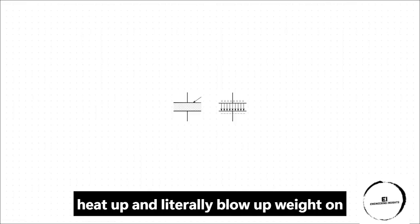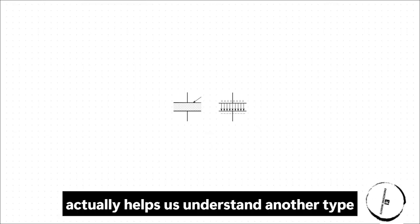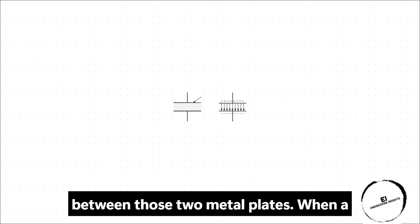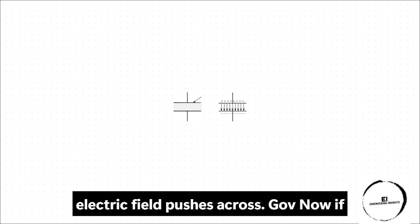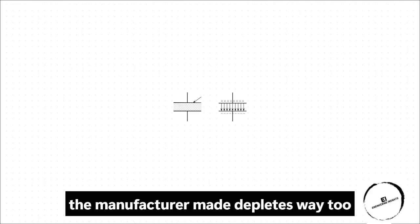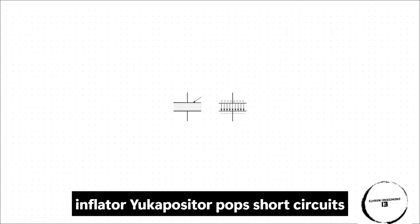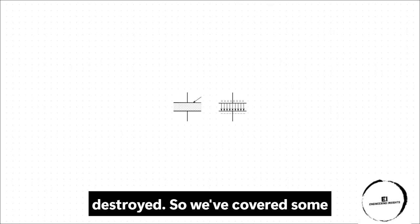No joke. And knowing that actually helps us understand another type of catastrophic failure, dielectric breakdown. Think about the dielectric material, the insulator, sitting right between those two metal plates. When voltage is applied, an incredibly intense electric field pushes across that gap. Now, if you push the pressure too high, or if the manufacturer made the plates way too close together, that electric field becomes overwhelmingly strong. Eventually, a spark will literally jump across the gap, totally breaking the insulator. Your capacitor pops, short circuits, and the whole shebang is completely destroyed.